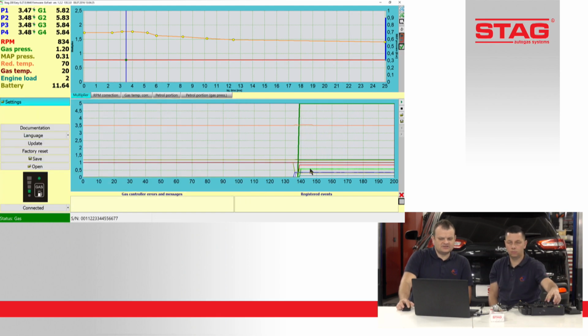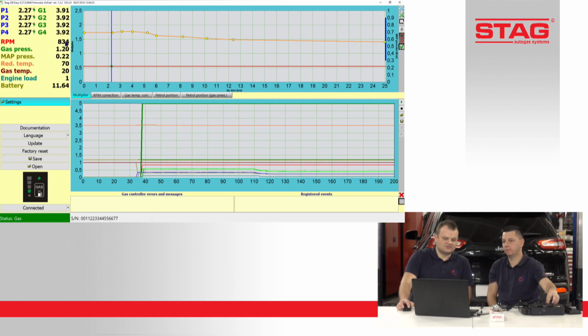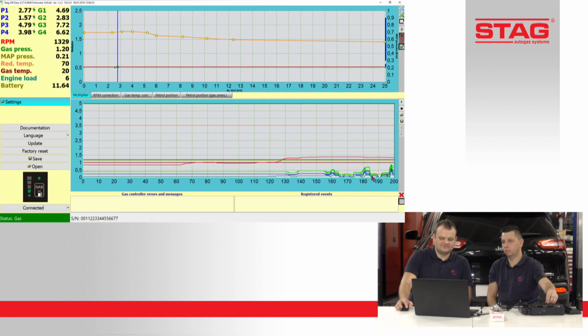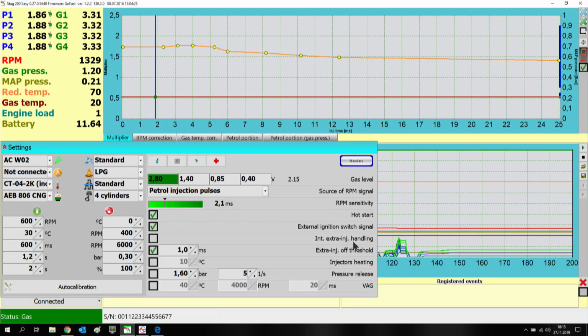As you see, these are stable petrol timings. Now it is 2.3, for an example, in stable conditions. If during stable conditions RPM is on idle, or during driving at constant speed, the petrol timings are also stable. But sometimes you can see very short petrol, like now 0.1 or 0.2, like here. You see on the graph, in the middle, there is a near zero impulse, like 0.2 or 0.3. If this is occurring with jerkings, we can use this function.